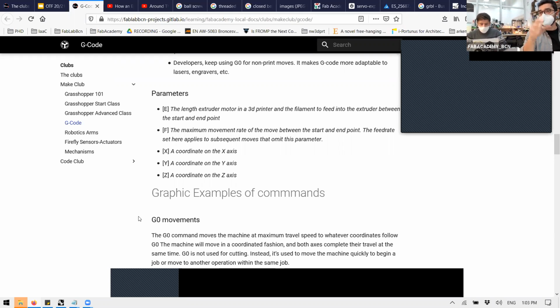G92 establishes this as the origin of the absolute coordinates, and then you said G1 extend. Each time you click, it's G1 extend, G1 extend. So actually you are able to send this automatically. For example, for this machine, we have a custom script to make the machine self-clean itself. That is code just by sending coordinates, compiling about 20 lines of Gcode.